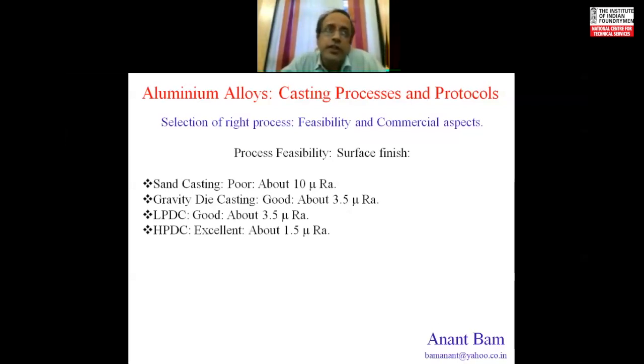HPDC coatings are nothing but lubricants, as they are called. They are either water emulsions of mineral oils or very fine atomized spray of mineral oil. It creates a very, very thin film on the surface of the die. The purpose of this lubricant is multi-functional. The first function is to create a physical barrier between the molten metal and the die material, thereby preventing any possible soldering.